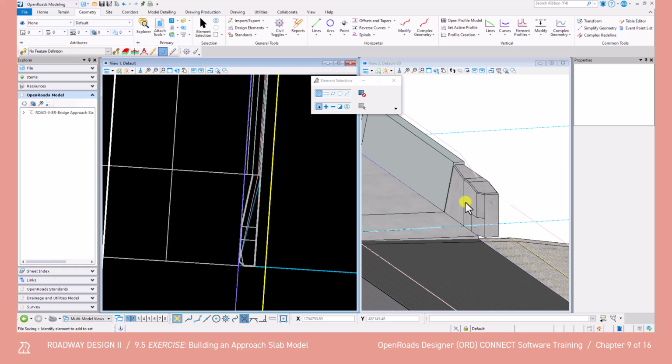So note that the only remaining step would be to change the bridge slopes from 4% to 2%. This would be done by creating a parametric constraint on the PSH lines in the main I-65 corridor model. The parametric constraint would be 90 feet from the start of the bridge to match the superelevation runout of the roadway. And note that for this parametric constraint to work on the PSH values, the PSH slope constraint rollover value will need to be turned off, meaning a separate template drop will be needed.